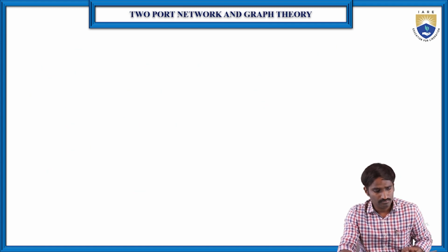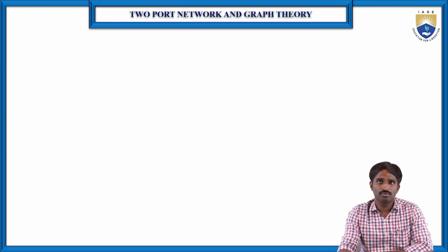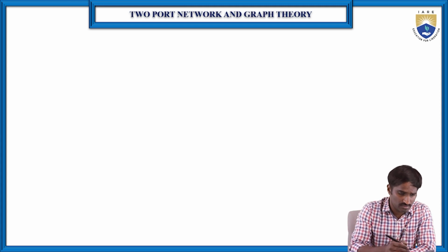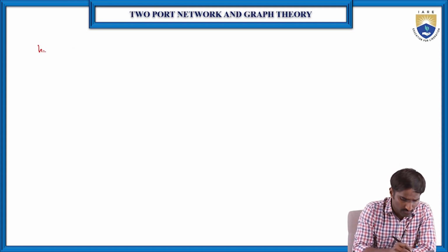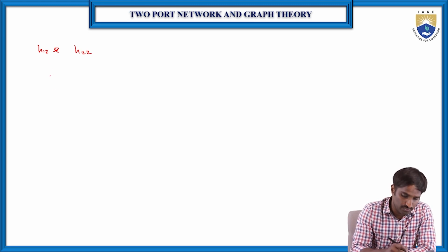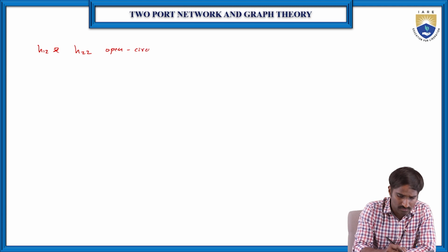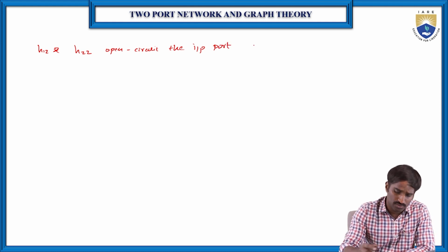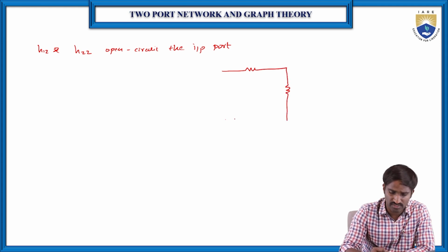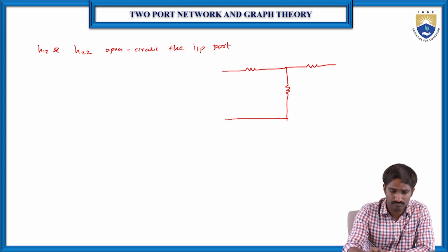Then coming to the other two parameters, H12 and H22, we open circuit the input port. Let me redraw the given circuit with the input port open.